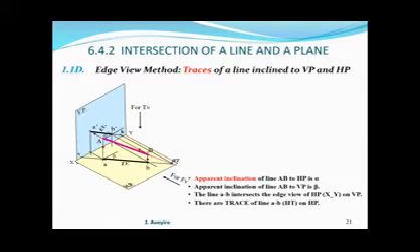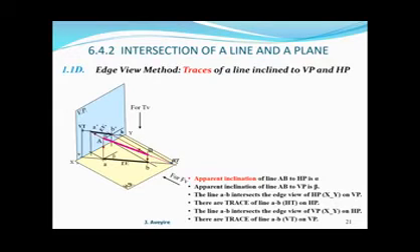We label that V. Then, to get the right point, we draw a vertical line there, look at the front view FV, and extend the line there, and that locates the vertical trace of the line. To prove it, we can extend the line from that place to show that it is the actual line. So we have the traces VT and HT.